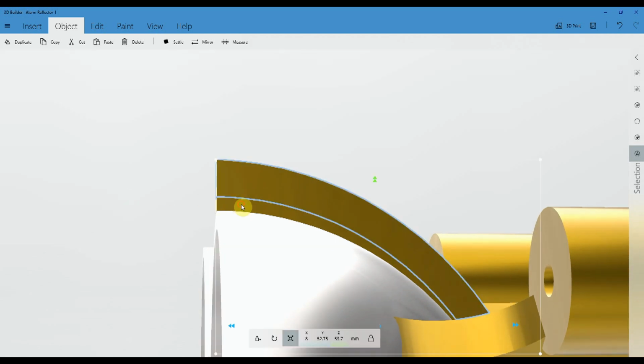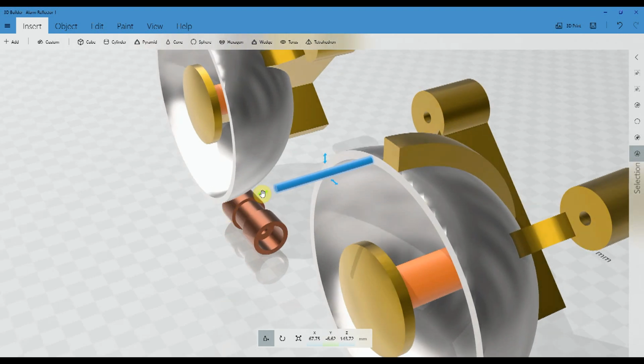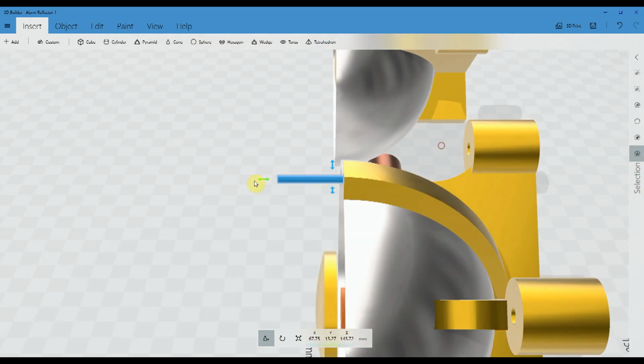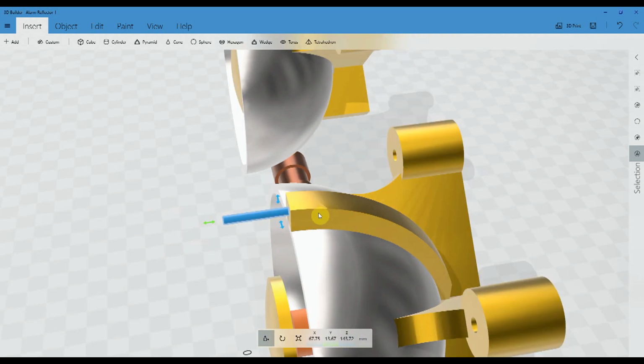It's just amazing. And then I'm going to add, I think it's a 2.5 millimeter hole in that, so that I can later on tap it. But in the end I just basically imported an M3 thread that it can tap, which is absolutely amazing. So I can just align that and get everything done for this one before I start copying and rotating it.